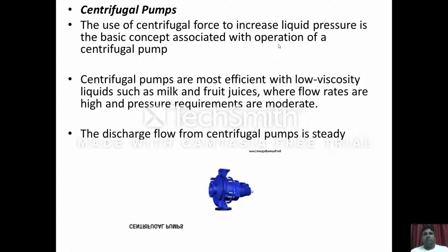Now I'm coming to the pumps. In any industry, generally there are two types of pumps used for the transportation of liquid. One is the centrifugal pump, and the second is the positive displacement pump. I may be running a bit fast. In case of the centrifugal pump, the working principle is that centrifugal force increases the pressure when it rotates inside a casing. I'll show you a video. Due to rotation it creates some kind of suction, and later the liquid comes out from the periphery.